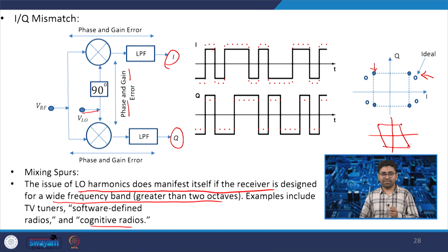So, these are the merits and demerits of the direct conversion receiver. The merits we already have seen: the problem of IF is solved, the problem of image is solved, and single chip solution is possible instead of a multiple chip solution. We can easily filter out and select the channel. So, this is how the direct conversion is beneficial.